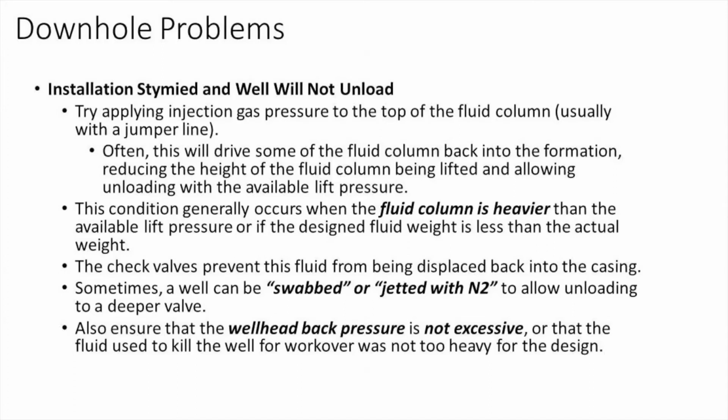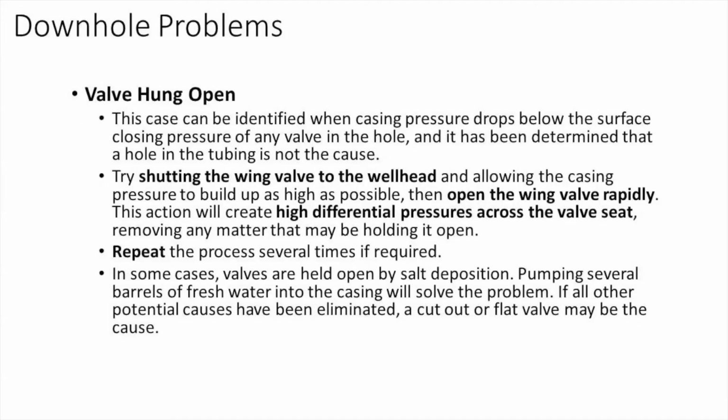So wells not producing, wells not unloading, basically we have a dead well on our hands. Again, this can come from a couple of different conditions, such as poor design, a design that was made for lower fluid rates than what the well can produce. A change in well conditions, changes in water cuts, and formation gas volumes can cause these issues and force a workover to be done to remove the equipment and replace it with a better performing design.